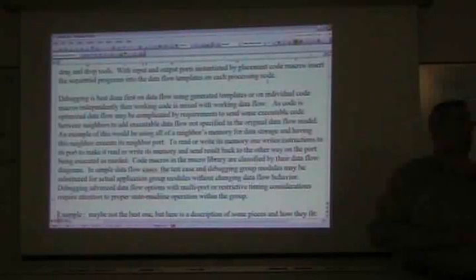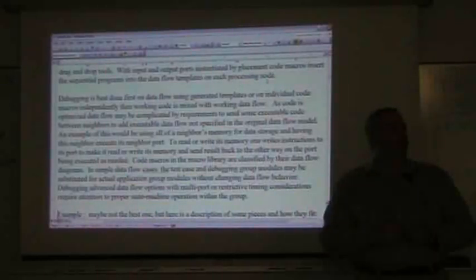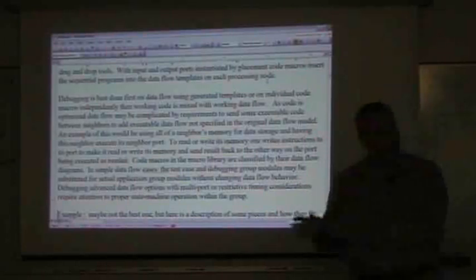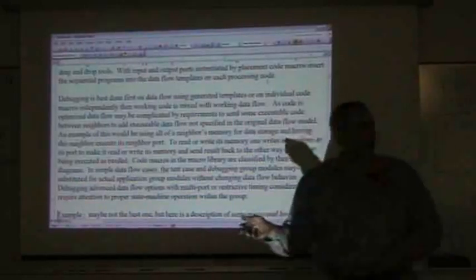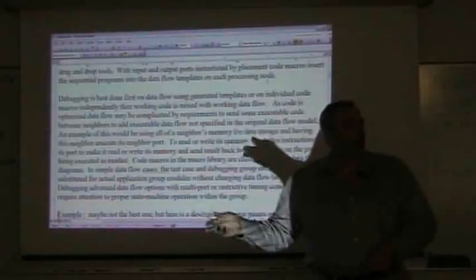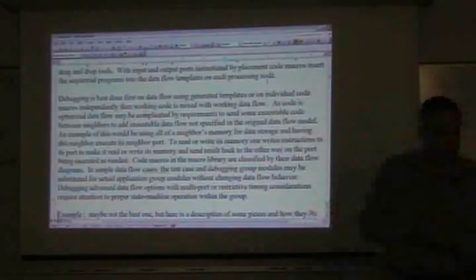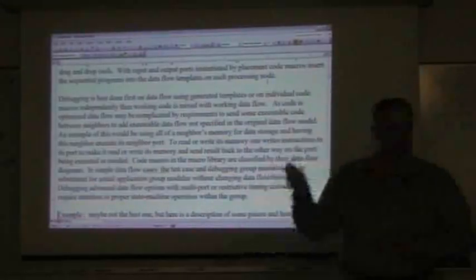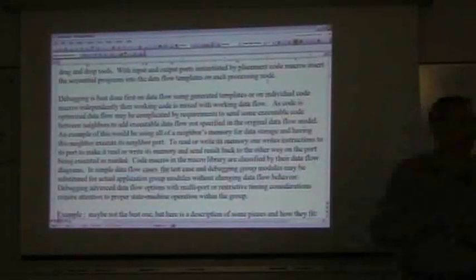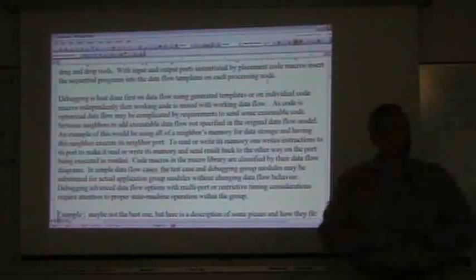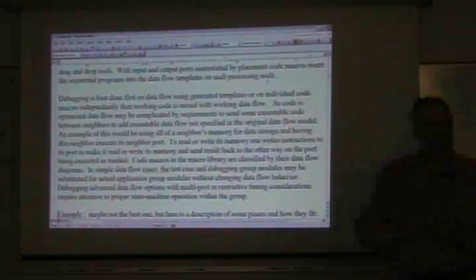When that node gets a value, actually it's talking to the linearizer node. I split these. So the sample node gets a sample and hands it to the linearizer node. The linearizer node sends a message to the neighbor that's reading its port that has nothing but data in it to take this value, use it as an index, look it up in your memory, and send it back to me. The code is literal: A store, fetch from A, store P plus, store back to the program counter of the port that I'm in.